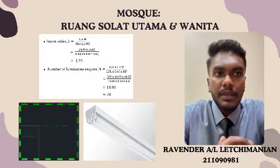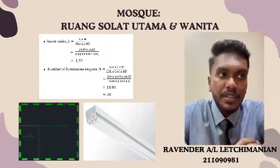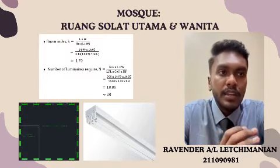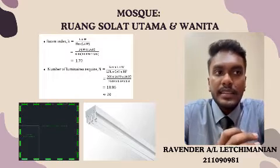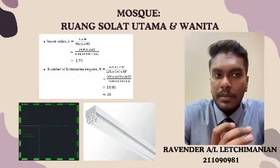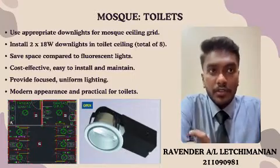The TLD standard lamp type also offers good light quality with options for color temperature and a lifespan ranging from 10,000 to 20,000 hours. So the TLD standard lamp type is the most suitable for this larger space and reduces maintenance cost due to the higher lifespan. Now let's talk about the toilet at the mosque.